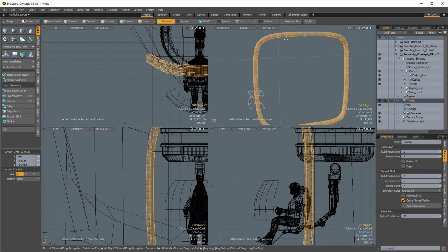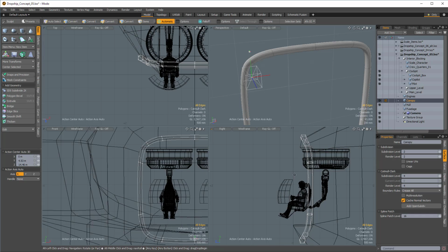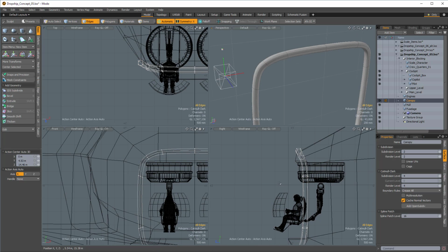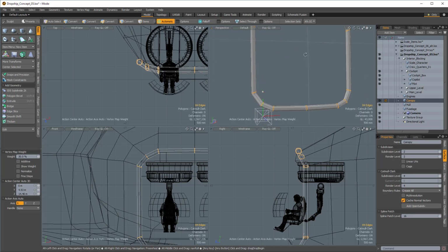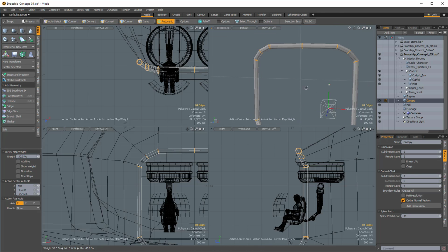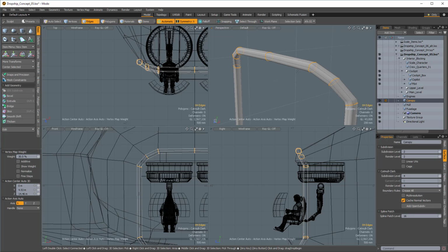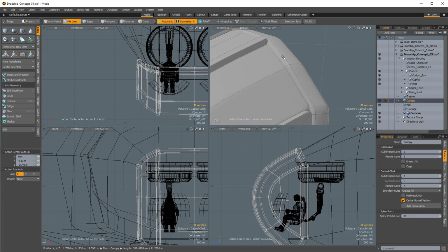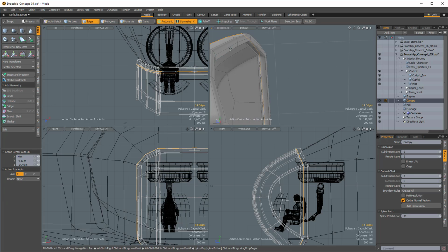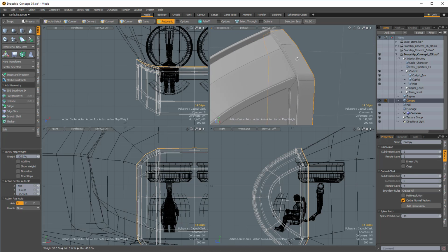And I think what I'm going to do here is I'm just going to select all of the loops going this way. So I'll just select through here on the side view, press L to get my loop, and then the open bracket key to invert my selection, and then I'm going to weight all of these edges. So basically I'm giving it back its polygonal structure for the most part, but I'm just getting a little bit of rounding. So now when I unhide this other stuff, I should be able to see this. Now there are going to be some other edges I might want to weight, so maybe right here and right here I'm going to add in the weight.